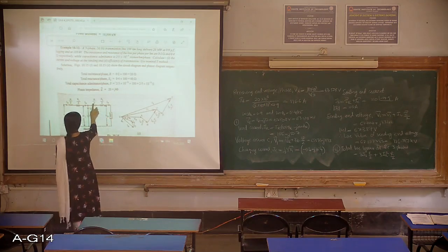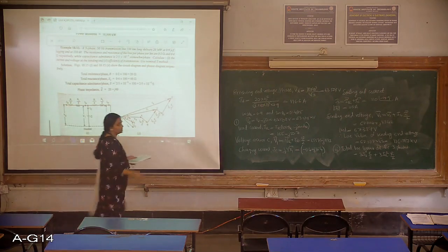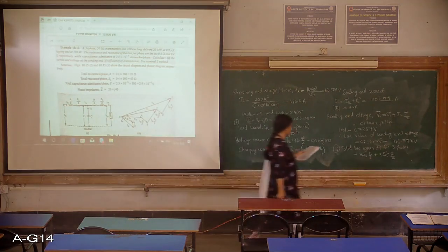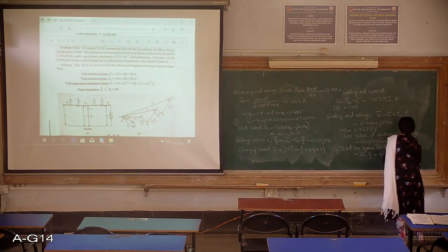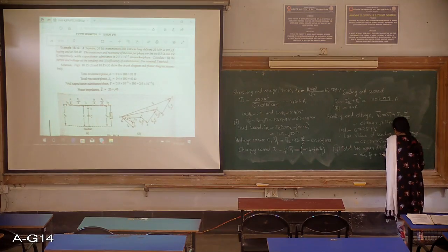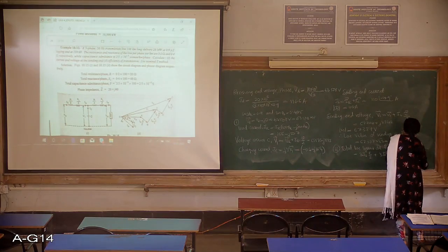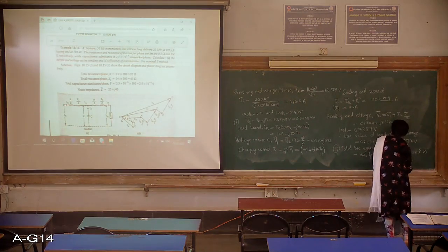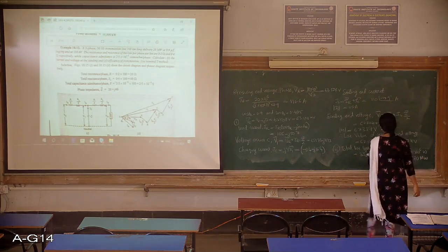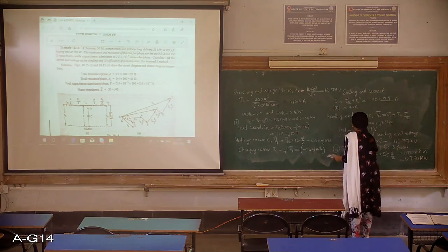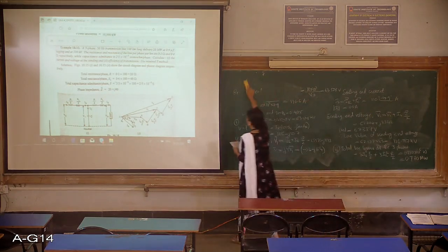Okay, so here it is IR, here it is Is. 3 lines, so 3 times the drop. So you know all the values, so substitute here and you just take the magnitudes. So this comes out to be 0.770 into 10 raised to 6 watts. So 10 raised to 6 is nothing but mega. So you can write it as 0.770 megawatt. This is your losses.